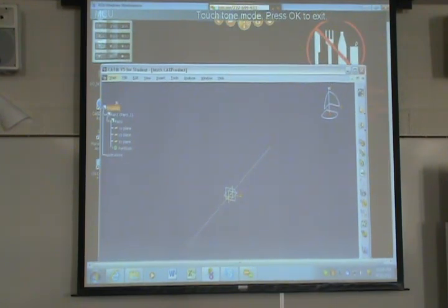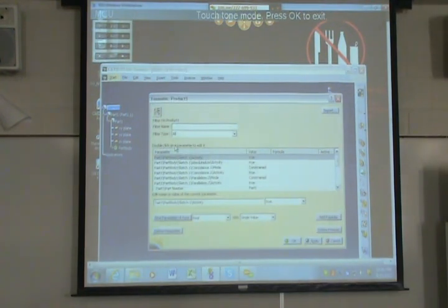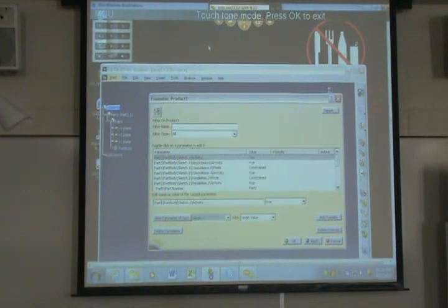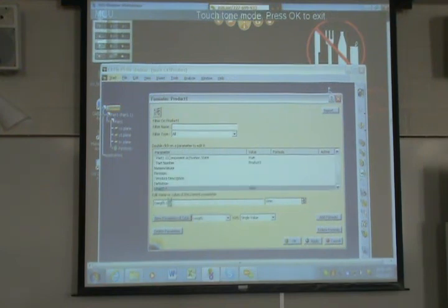Okay, so if I double click on the product, I am now in the skeleton level, and I want to make sure that the skeleton parameters I create are inside the product. So I'll go to Tools, Formula, and do a new parameter of type length. We're going to make it a single value. If I press new parameter of type length, it'll pop up this little dialog, and I can name it whatever I want. I'm just going to call it length.